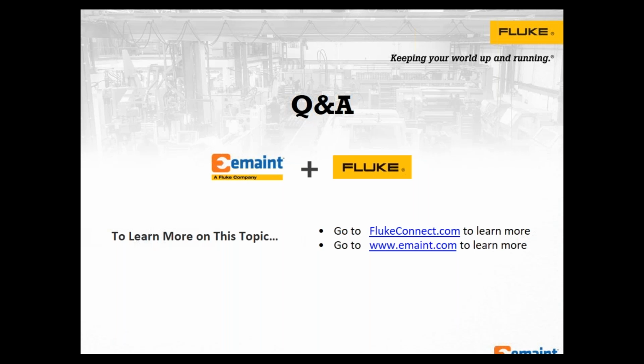That's reasonable, that's cost effective for you, but if you go in and check the calibration, keep in mind that every time you calibrate a particular device, you introduce more variability. So it's best practice to check the calibration and not make any changes unless it's not within the specification. After a period of time, you see that after checking the calibration or PMing it, there's really no change that occurs, and there's no need to go out there as often. But you don't know this until you actually do the work.